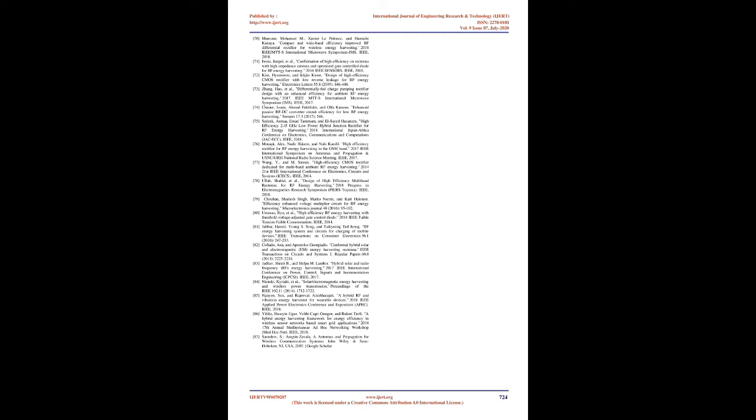To harvest solar energy, an MPPT algorithm, the P&O algorithm, is used with an antenna made up of a microstrip feed patch operating at 2.4 GHz. The circuit is reported to produce a power of 9 watts. Nakata et al., 2014, proposed an energy harvesting scheme that incorporates solar and antenna structures as the source for energy harvesting circuits. This scheme uses solar to electromagnetic converters to supply the required power for RF signal generators. They also verified some new topologies to reduce the rectifier sensitivity to the received RF energy levels.